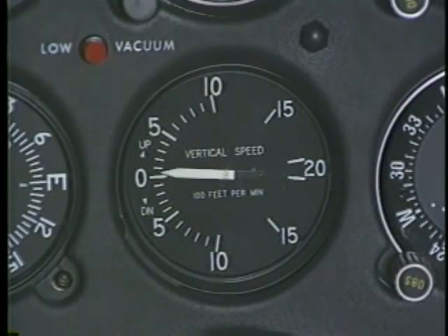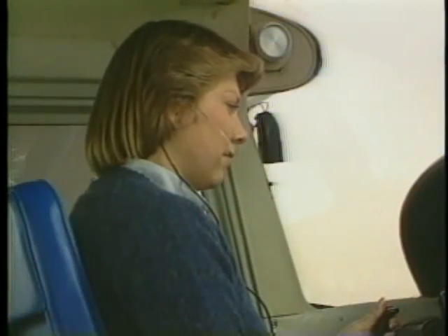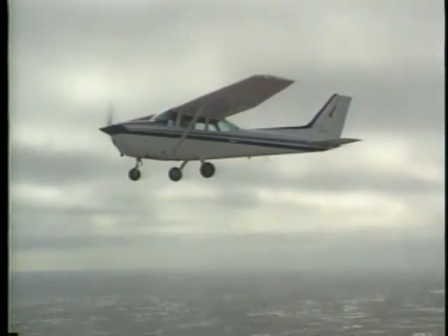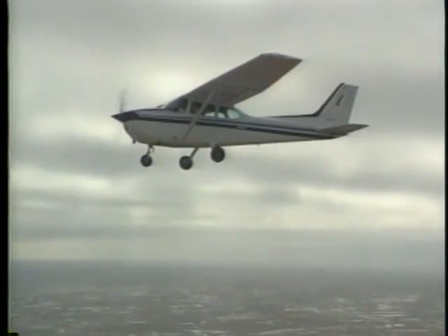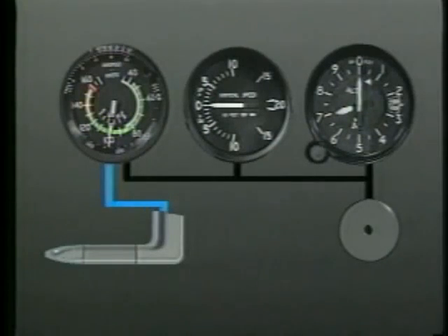When a change in altitude occurs, the VSI immediately registers the trend of movement. It then stabilizes to show the actual rate. As an instrument pilot, you should be aware of the erroneous readings which can occur if the pitot-static system becomes blocked by ice, dirt, or even insects. If the pitot tube becomes blocked, two types of errors can occur with the airspeed indicator.